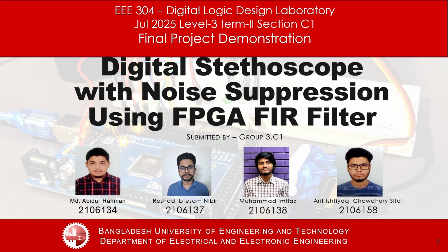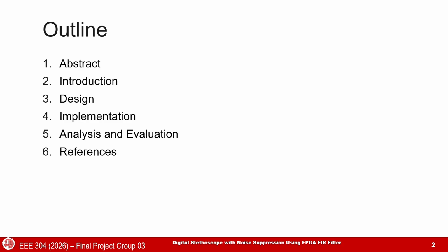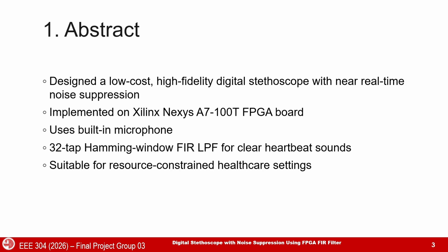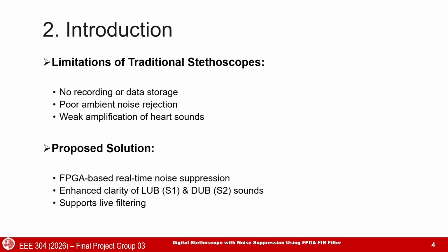Our project is a digital stethoscope with noise suppression using an FPGA FIR filter. Here's the outline of our project. Our goal was to design a low-cost and high-quality digital stethoscope that can perform real-time noise suppression on the Xilinx Nexys A7-100T FPGA board using the built-in microphone. A 32-tap FIR filter is used to extract a clear heartbeat sound. This system can be very useful in healthcare environments.